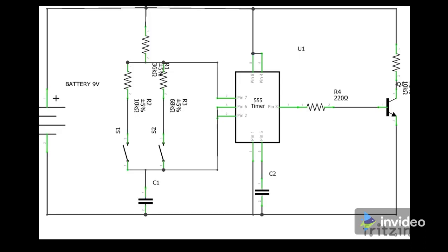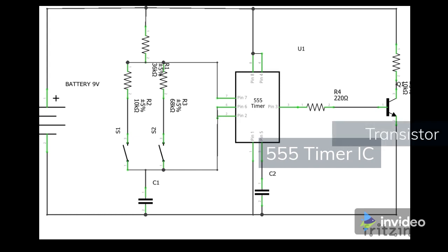The above given servo motor driver circuit diagram is not much difficult to understand. To drive the motor, we first need the PWM pulses, and that's why we are using 555 timer IC, while the transistor is there in the circuit for the amplification of signals. For the output, we would connect the VCC wire at VCC, GND with the ground and PWM wire at the collector side of the transistor.